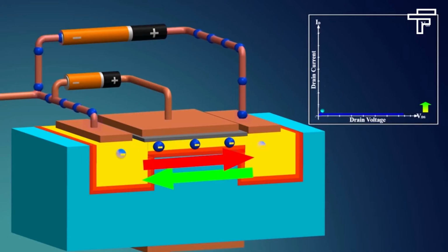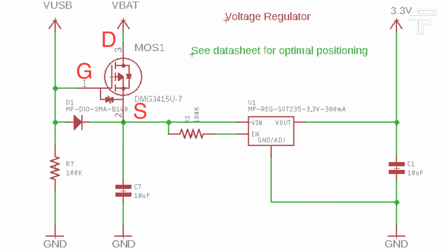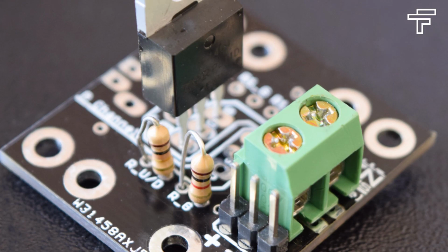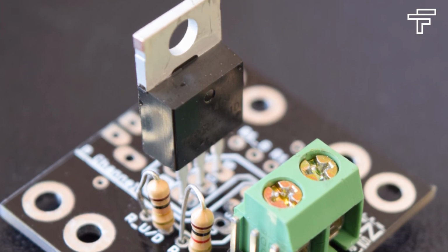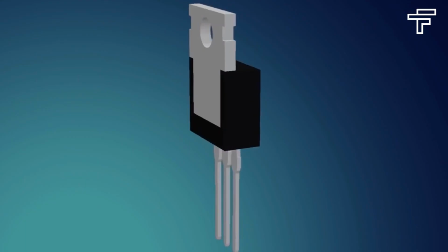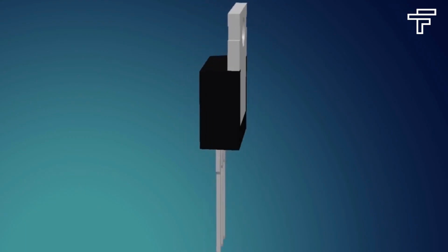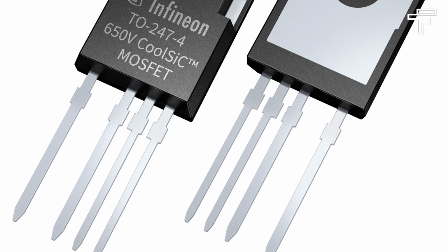The channel width and drain current will increase when the bias voltage increases, but if the applied bias voltage is 0 or negative, the transistor will remain in the off state itself. MOSFETs are ideal for use as electronic switches or as common source amplifiers as their power consumption is very small. Typical applications for metal oxide semiconductor field effect transistors are in microprocessors, memories, calculators, and logic CMOS gates, etc.